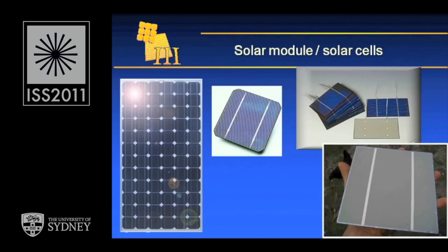This is another view of a solar panel shown here. This is the silicon solar cell. It's made from the element silicon that is cut into these very thin discs, such as shown here. You have an electrical contact on the front of the cell, and then right over the back, as shown here, you put some metal interconnects, solder them to the front, and interconnect the cells in series within this module. So all the cells are connected one to the other to produce the final module.